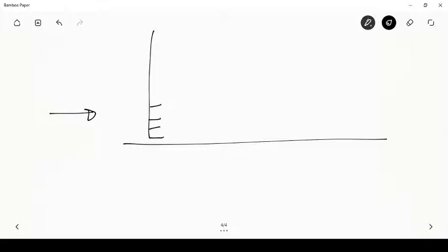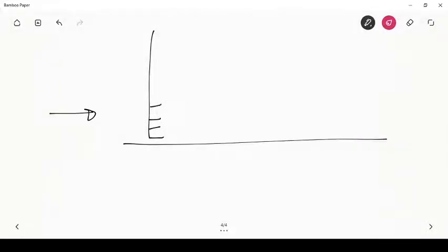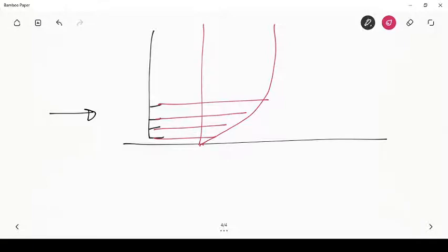Okay, so if I do a similar experiment on a flat plate, so let us say there is flow going here, and I put multiple syringe injectors, then the velocity profiles went higher and higher in speed as you go there, and less speed when it goes here. So you have a profile which looks like this, and the velocity is 0 at the surface. So this was something which is possible to observe. That is one thing. So we were able to visualize the edge of the boundary layer. You inject it at different locations, the edge of the boundary layer is different. So the thickness of the boundary layer can be found from there. So this is one thing that could be observed.